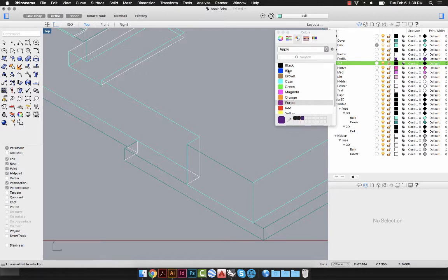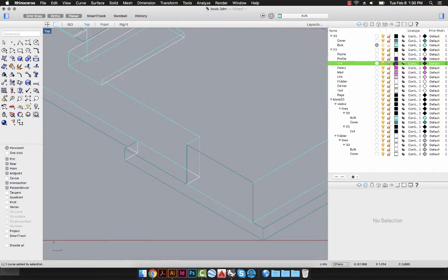I'm going to save that swatch there. You can see what I'm doing here, and then I'm going to replace it with that. So I'm just setting up a color scheme for my layers in order to understand what line weights they are. Usually I will do a monochrome scheme. Here I have pinks and purples, and the darker the color, the heavier the line weight.